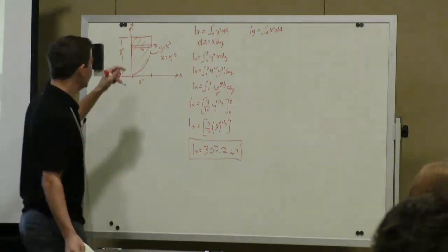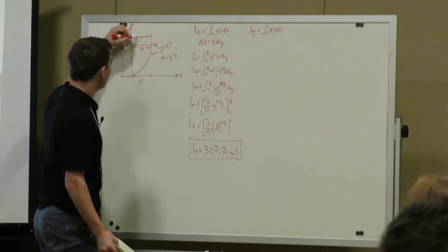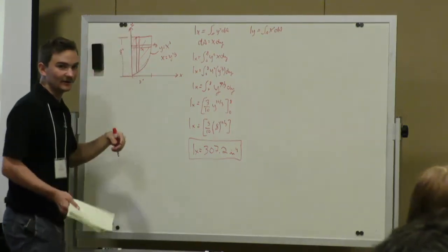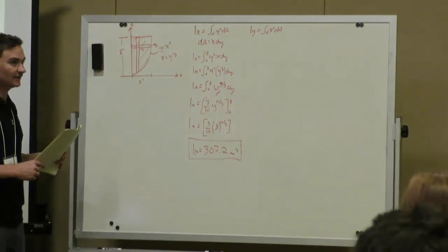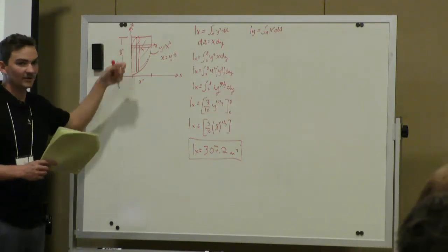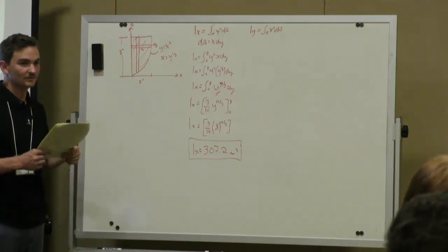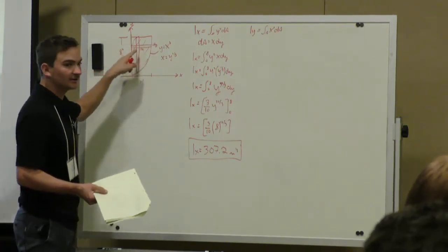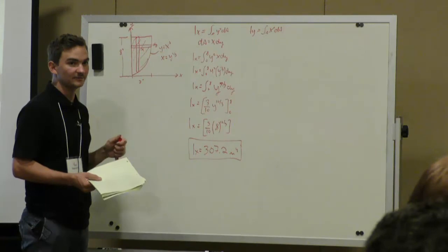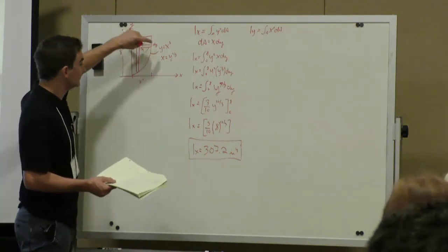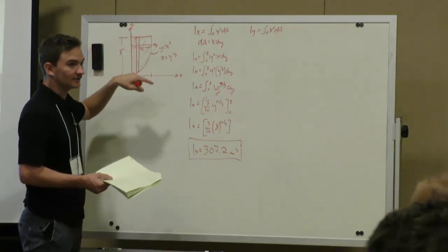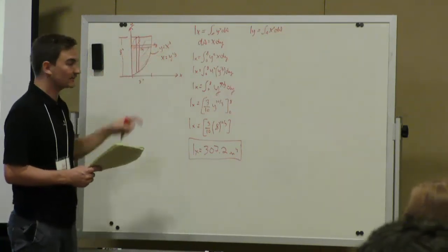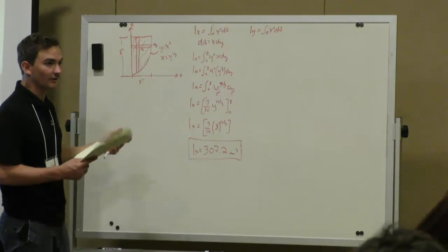Yeah, very good. So we will always want it to be parallel to the axis. Ideally we want it parallel, but sometimes it doesn't work out that way. So what happens if we take it perpendicular? Yeah. The reason we choose parallel is because if you use perpendicular, you have to use the parallel axis theorem. So you have to take the moment of inertia, in this case of a rectangle, plus x tilde squared dA. So that's why we choose it parallel, to avoid that.